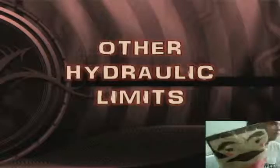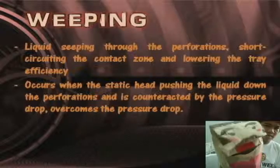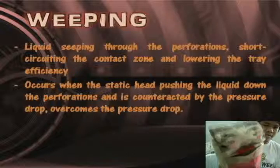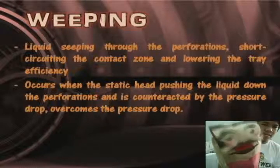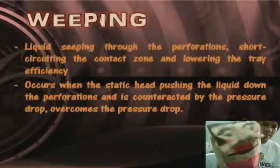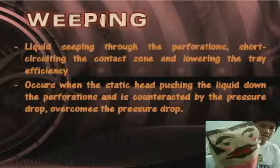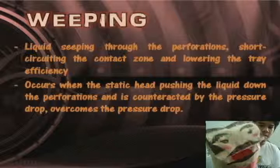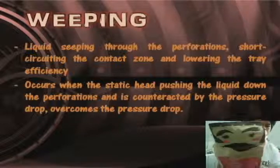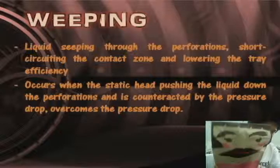Other hydraulic limits. Weeping is the liquid descending through tray perforations, short-circuiting the contact zone and lowering the tray efficiency. It occurs when the static head, used to push liquid down perforations and counteracted by the pressure drop that holds the liquid on the tray, overcomes the pressure drop. Weeping is mainly affected by the fractional hole area. When the area is larger, gas pressure drop is smaller, and weeping tendency increases.